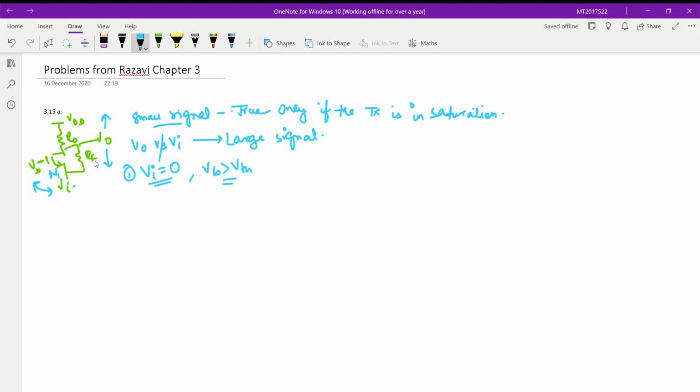So what will that depend on? How can we say that VO is low or not? That will mostly depend on RF, right? If RF is small, then when we turn on VB minus Vi, RF will draw in some more current, and thus Vout will go down a little bit.